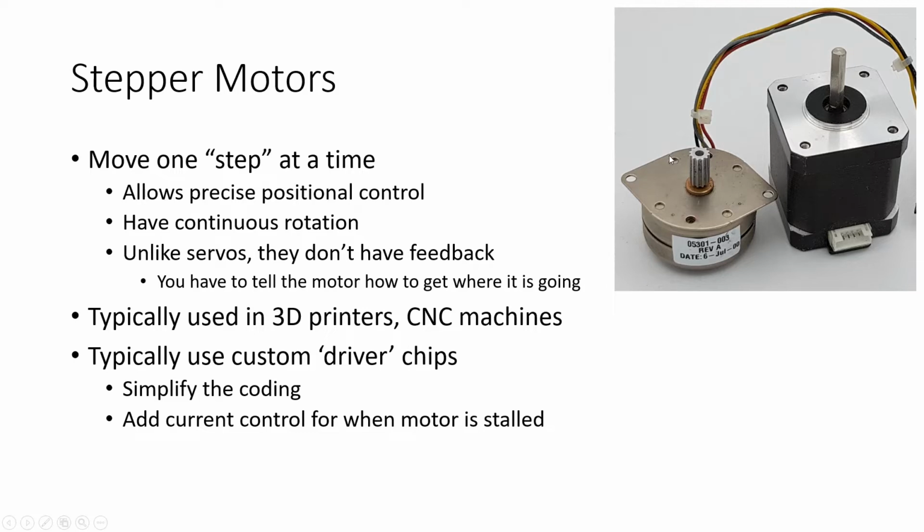So really good for CNC machines, 3D printers, and things like that. You can use those to drive belts. The catch is that the stepper motors don't actually have any feedback. You tell them to move a certain amount, and if they're stalled or overloaded, you don't necessarily know whether or not they've completed that command for you.